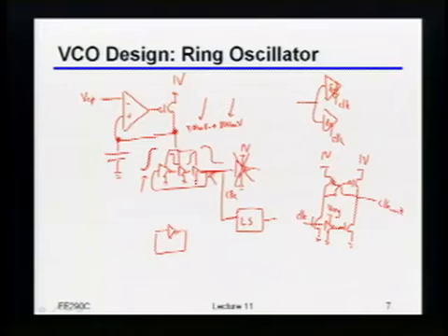Okay, I think what you said was correct, but I just wanted to give a more intuitive explanation. Let's even assume that I have a fixed regulated voltage. In order to cause this thing to rise, I basically have to make this go high, which pulls this down, which then turns on that PMOS, which then finally makes this go high.